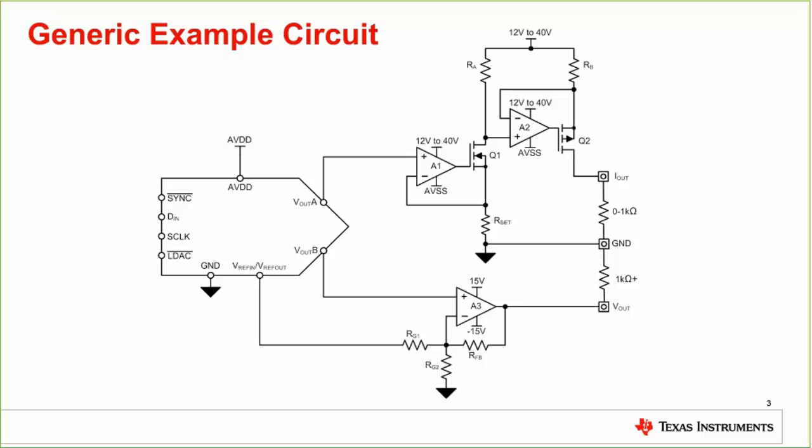Meanwhile, for the bottom half of the circuit, we have just a simple gain stage, because typically the DACs that are available are SPI interfaced and relatively low voltage devices operating off of maybe 5.5 or so volts with output spans from 0 to 2.5 or 0 to 5 volts. For industrial, we want to see at most plus minus 12 volts. So we need a simple gain stage in order to realize those output spans. The minimum impedance for the voltage output is about 1 kiloohm and upward. You typically don't see anything less than 1 kiloohm for the voltage output.